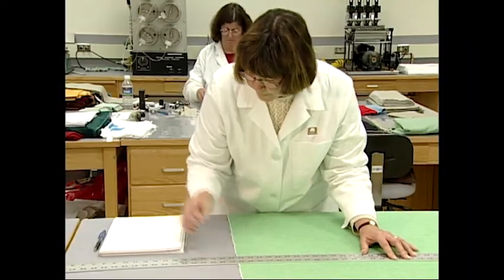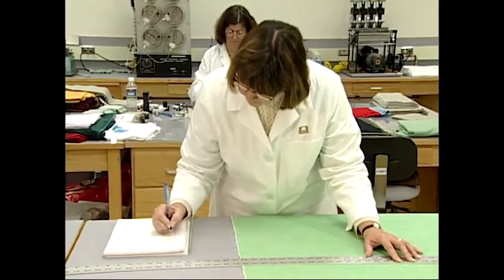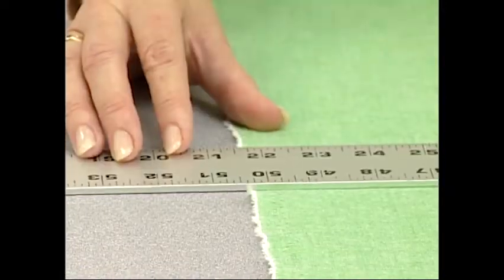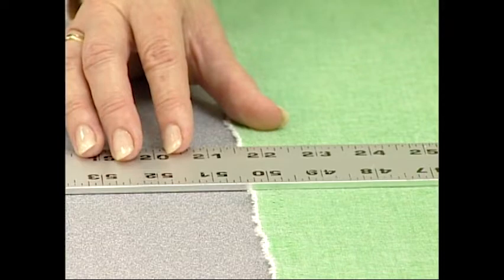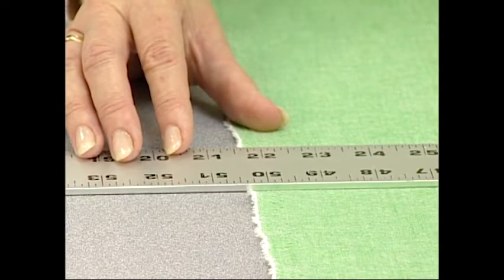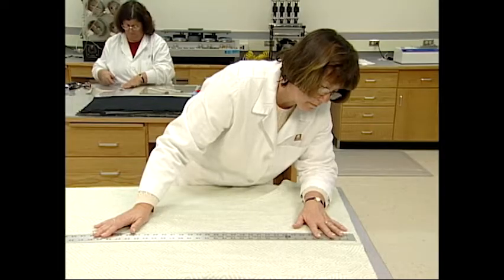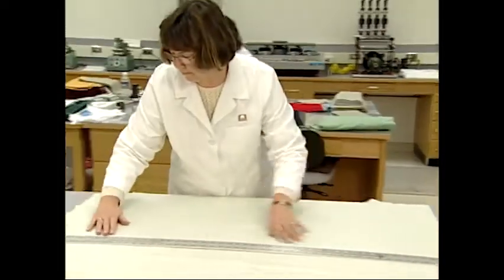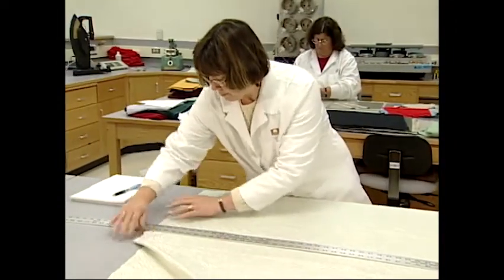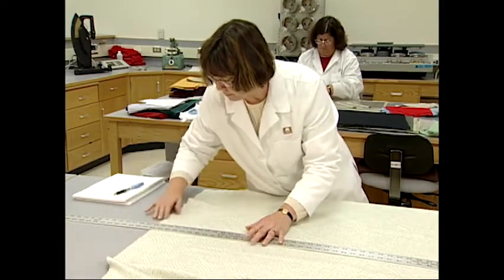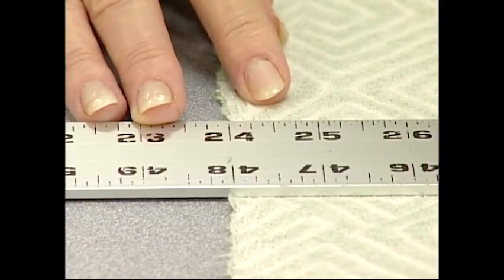Generally, the usable width of a woven fabric is over the selvage, but inside the fringe of the fabric. In this example, the measured width is 50.25 inches. Open width knitted fabric is normally measured between pin marks from finishing or inside the gum if gummed and trimmed as a precaution to curling during cut and sew. Shown first is measuring inside the pin marks. The width of this fabric is measured at 47.5 inches.